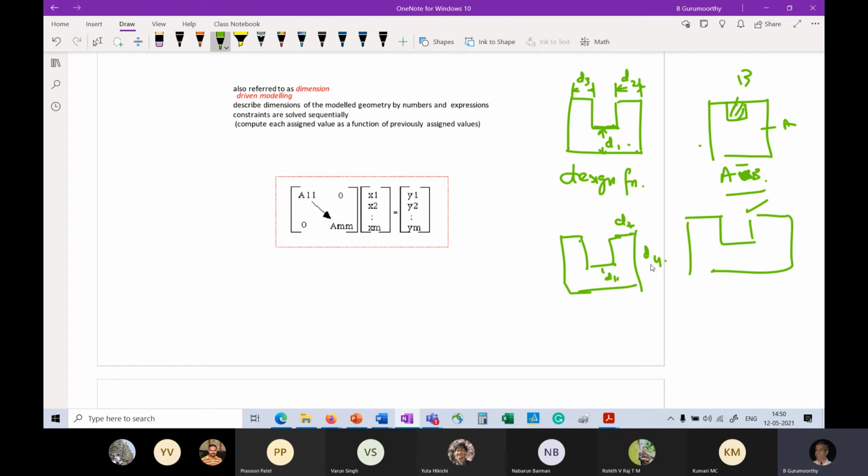So that was the idea, right? That designers who are actually designing the shapes, not modeling the shape, but designing the shape, are not thinking in terms of Boolean arithmetic or Boolean algebra. They are thinking in terms of functional elements and the parameters that control that functionality, right? So in some sense, you can think of the D1, D2, D3 as one way that the designer has parameterized the design. Meaning he has decided or she has decided that these are the dimensions that control my design.